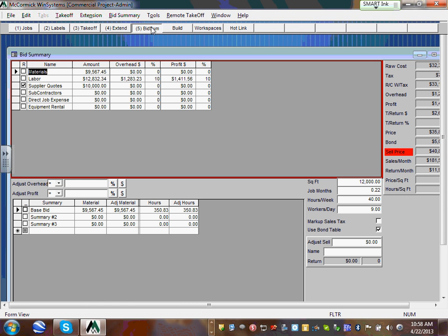Before I let you go with that one, remember we're using EMT in the ceilings. We're using MC cable in between all these metal studs in the building, so you're going to be looping them. When you draw, and when you get me your paper, I would like to see colored feeders going all the way to the panels.